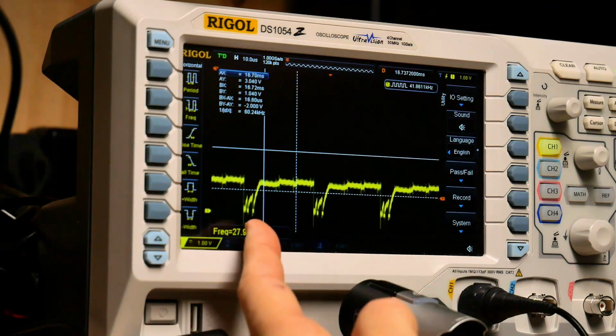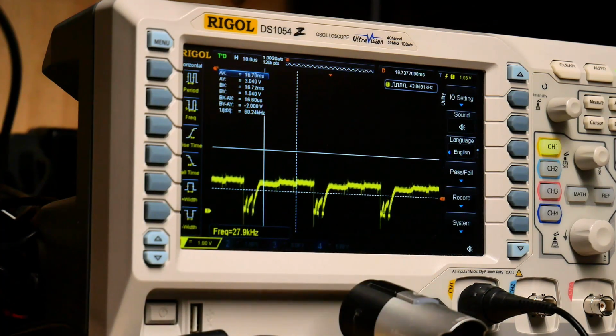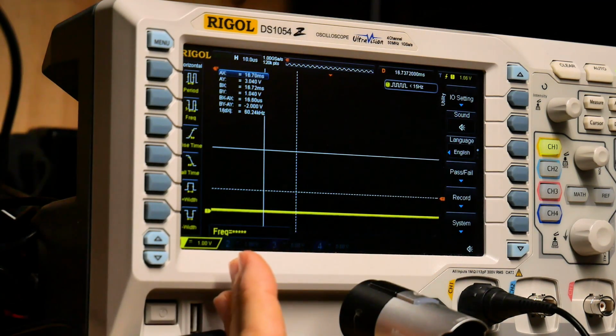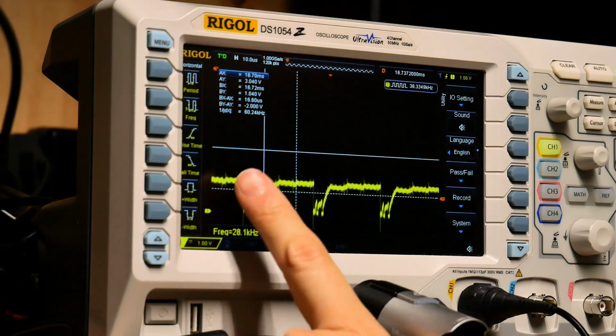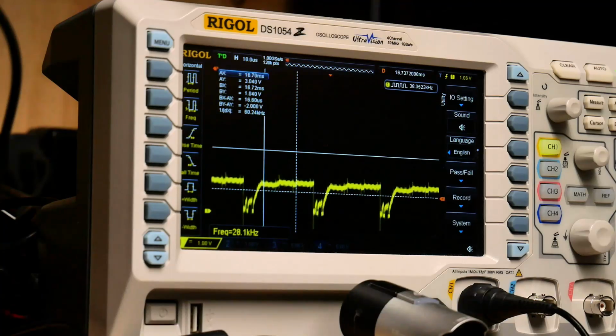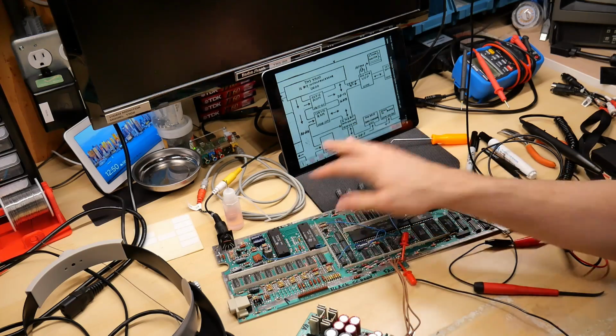Actually, we were seeing this on the other VDP, right? Let me swap back to the other one, just make sure that this signal looks the same. Okay, I've switched back to the VDP I got in the mail call video. Let's look at these pins again. Okay, so this is the right chip with the other VDP, and we're seeing the exact same thing going on here. And this pin as well is screwed up. Okay, so I saw absolutely no change with the two VDPs. Both of them look the same.